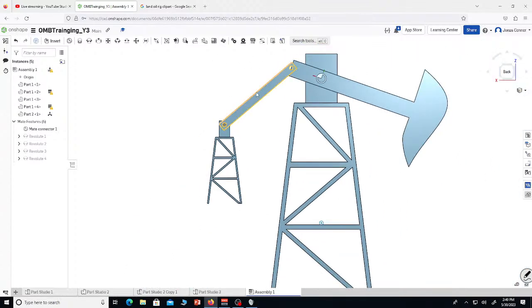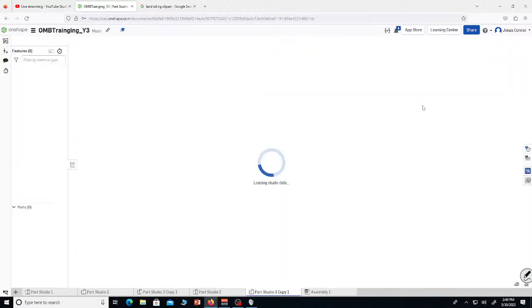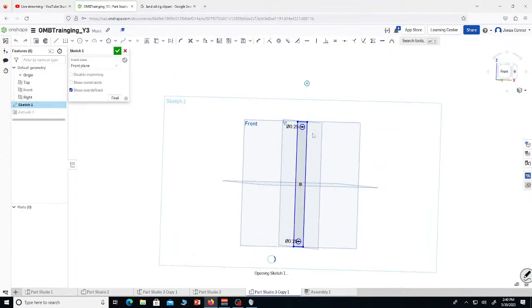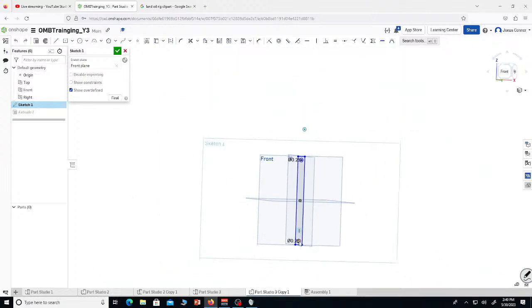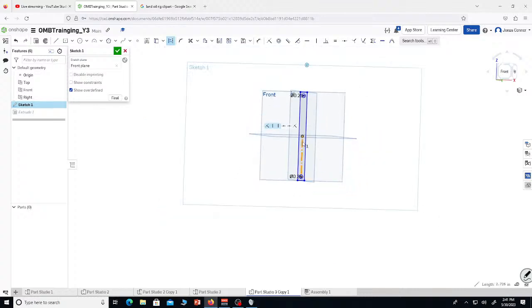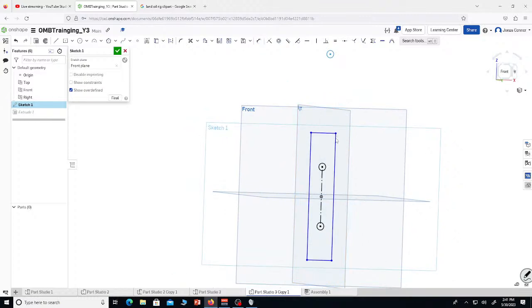So what we'll do is instead of this bar, we'll have this bar, we'll duplicate this. And then we'll shrink this, we'll make it shorter. So in the sketch, we'll just make these. So how far away? We'll create a line between here. Make that construction. Could do a dimension, but we'll do this instead. Make another construction line. Make these equal. The dimension one of them is, say, like 1 inch. And then we'll shrink this down a bit.